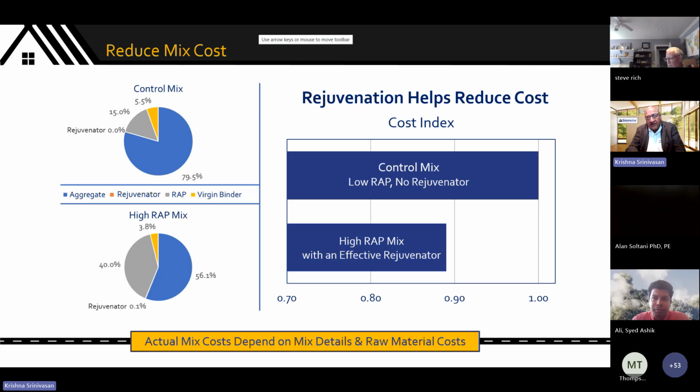And this is one of the dominant reasons, guys, I won't lie to you, why high RAP mixes have really taken off in the past, let's say 10, 15 years. One has been simply the availability of bitumen. Many parts of the world are net importers of bitumen, and with that come higher costs and higher regulations and things like that. That may be a driver.